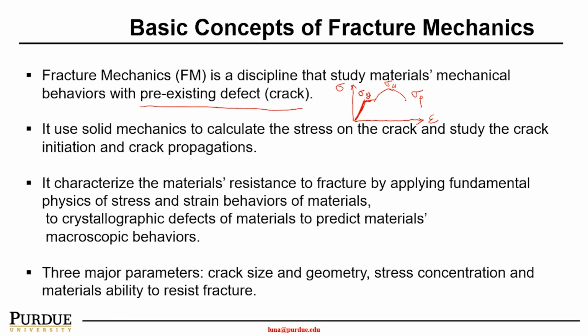Fracture mechanics uses solid mechanics to calculate the stress on the crack and study crack initiation and crack propagation. So if I have a material and the material starts to develop a crack, when the material has a crack during its service life, it may not be dangerous.